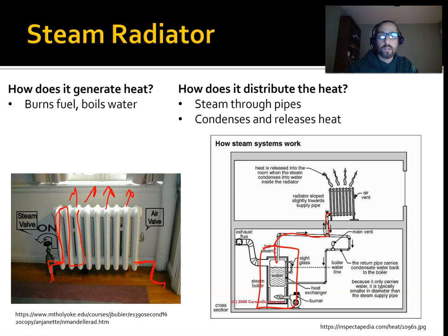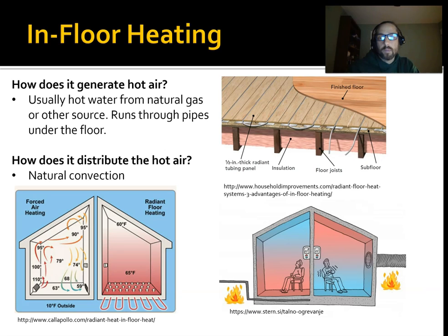But either way, you take the chemical energy, convert it into thermal energy in water and latent heat and vapor, and then you release that out as radiant energy. And again, it's a loop. The water comes back, drains back down to the tank, heats up, boils again, and so on. Okay. So that's a one-pipe system, which just means it drains back the same pipe.